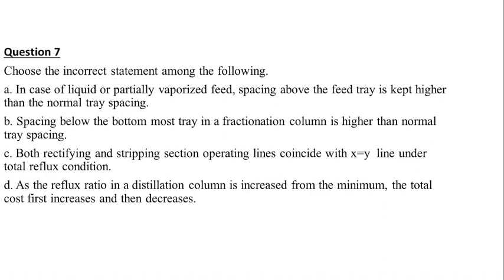Then both rectifying and stripping section operating lines coincide with the x equal to y line under total reflux condition. Under total reflux condition, R will be equal to infinite. The operating lines for rectifying and stripping section will be coinciding with the x equal to y line. Also, there will not be any bottom product drawn during total reflux. So option C statement is also true.